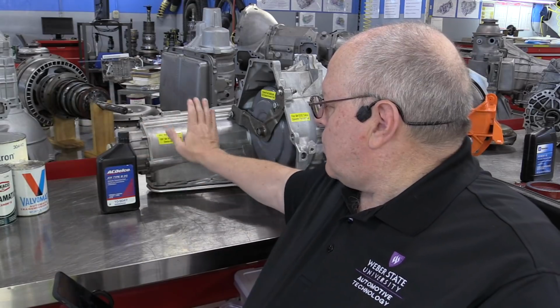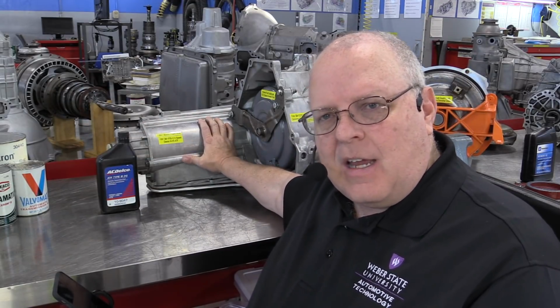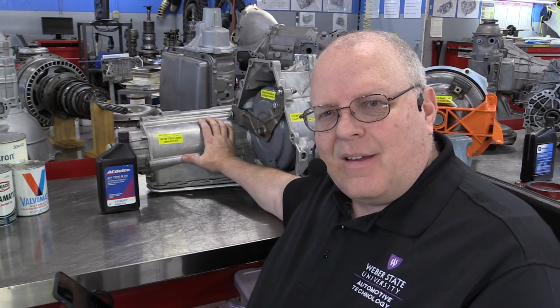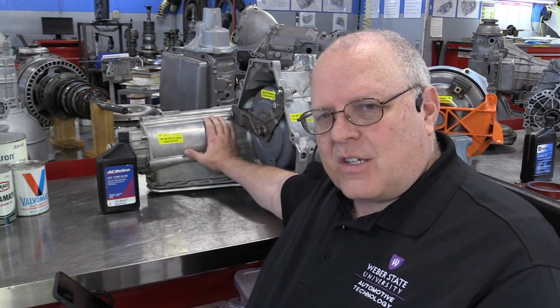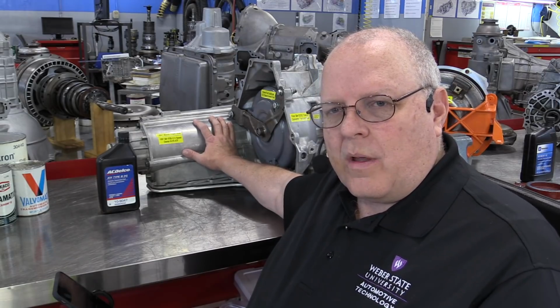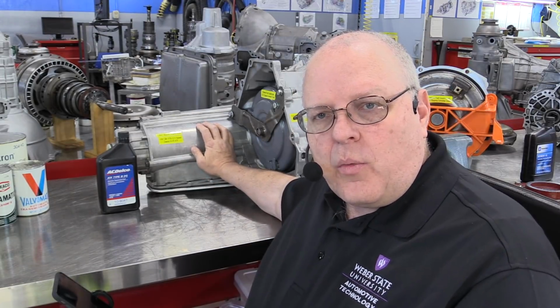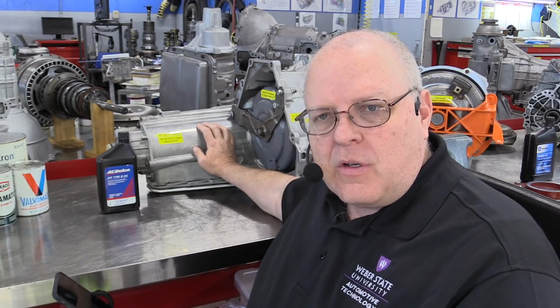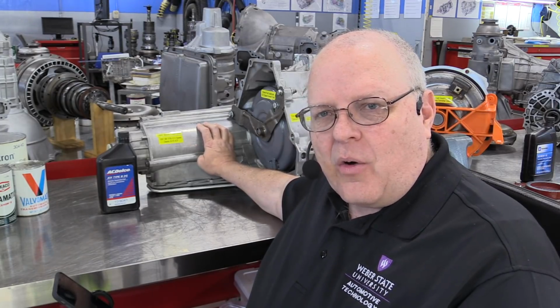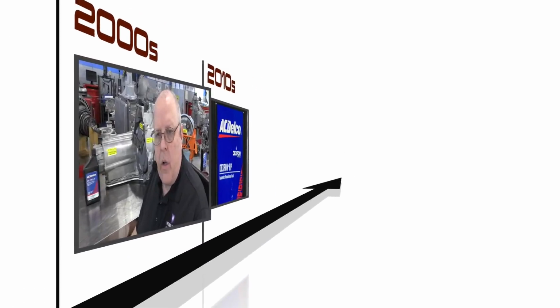So the original transmission fluid spec for this 4T65E front-wheel drive transaxle, here in 1997 model year, began with Dexron 3F. But because of the shuddering, they went to the Dexron 3G fluid specification in 1998 to try to correct a lot of this shuddering.